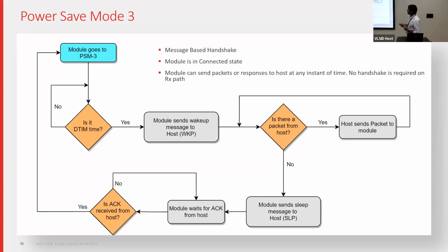It will also check if there is any packet from the host. If there are any packets from the host, the host sends a packet to the module, and this process will repeat until all the packets are completed. If there is no packet from the host, then the module will send a sleep message: I don't have any packets, so can I go to sleep or not? Then the host will give an acknowledgement that, okay, I don't have any packets for you. You can go to sleep now.